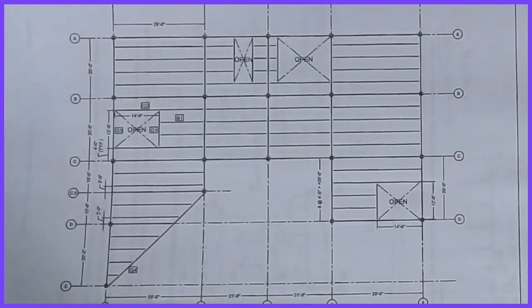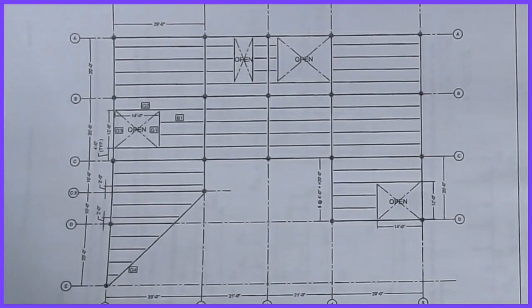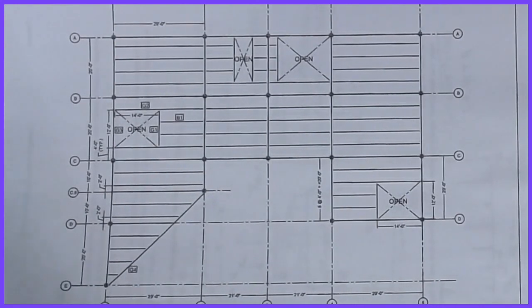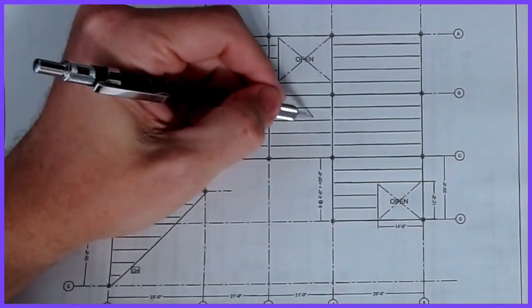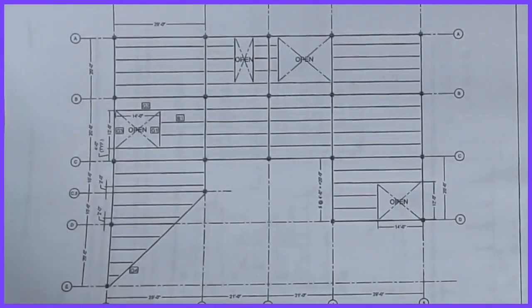So to start taking pressures from loads and applying them to a structure, you have to have some sort of framing diagram at your disposal. Now, what I've shown here is a typical plan view diagram. It's an irregularly shaped structure, but that's part of what the exercise is all about. If you say you have a dead load of 50 pounds per square foot or a live load of 100 pounds per square foot, or whatever the numbers are, that PSF unit indicates that it is an area load, related to the area on which it's acting. So a 1 by 1 square foot area anywhere here has the same value as one over here. It's still the same basic area.